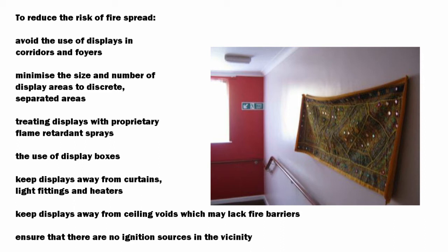Minimise the size and number of display areas to discrete, separated areas. Treating displays with proprietary flame retardant sprays. The use of display boxes. Keep displays away from curtains, light fittings and heaters. Keep displays away from ceiling voids which may lack fire barriers. Ensure that there are no ignition sources in the vicinity.